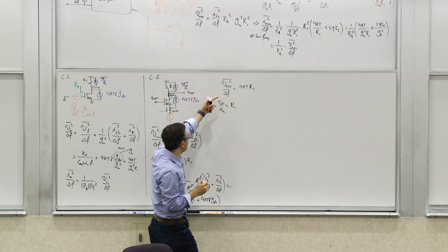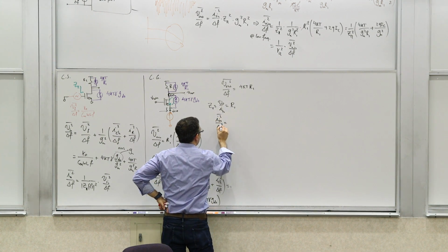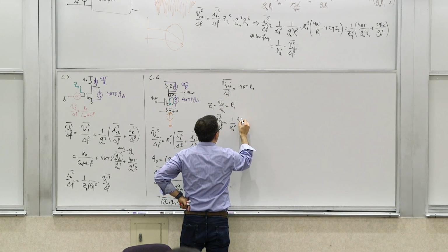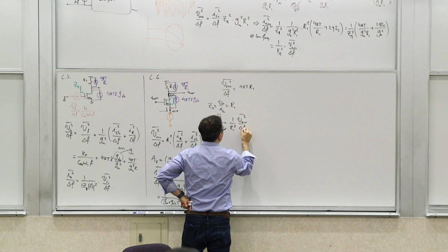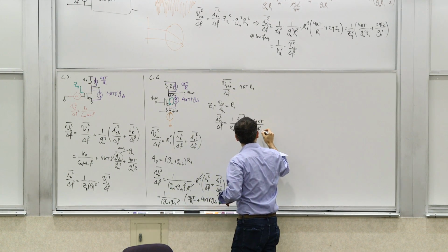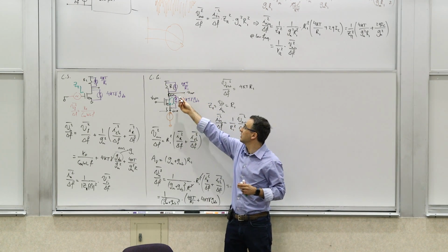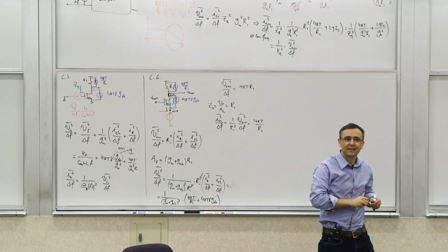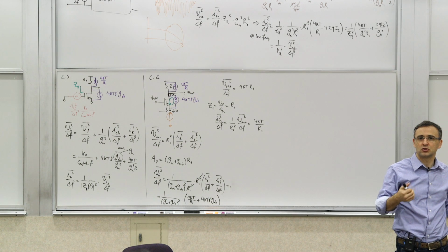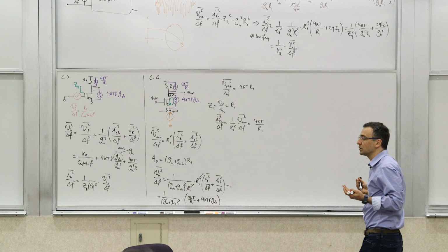And therefore, if you want to reflect that to the input, then I in squared over delta F, the equivalent input current noise, is going to be 1 over R1 magnitude squared times V out magnitude squared over delta F, which is going to be 4kT over R1, which should not be that surprising because this is the current noise at the output to begin with. And the current gain of this amplifier is 1. So it directly reflects to the input. It directly appears at the input. It's as if it's at the input.